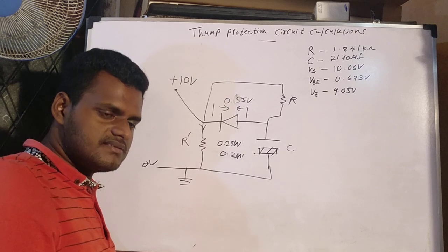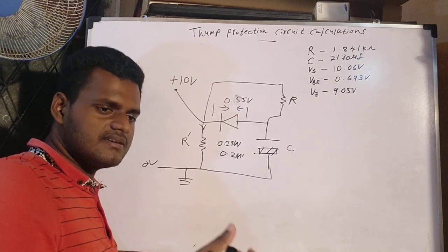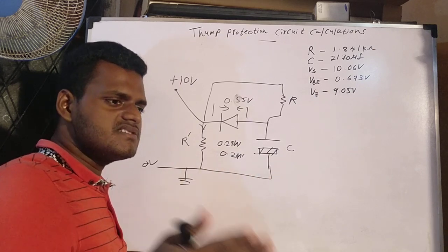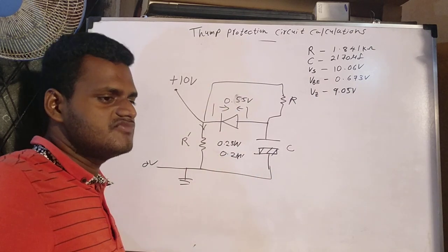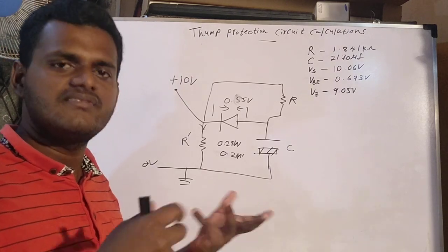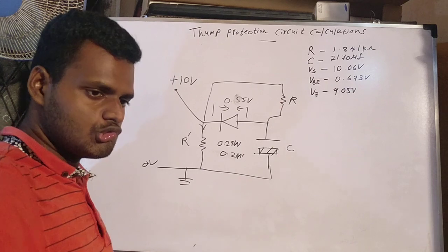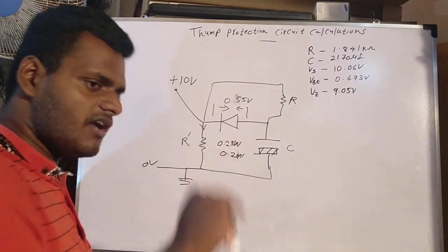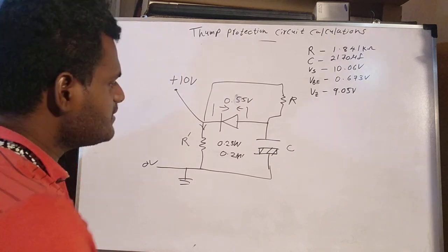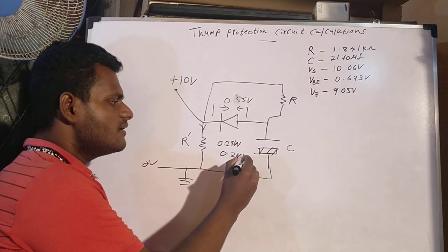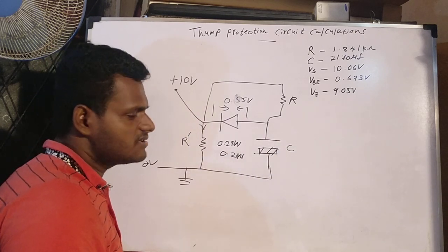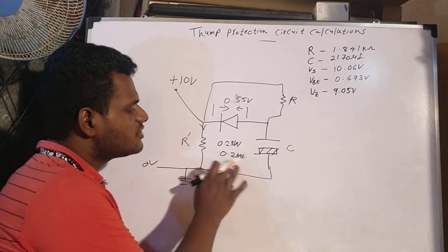If somehow it increases the energy again, the resistor will also burn. Otherwise, after some time, maybe 1 year or so, the resistor will also get damaged. So we have to do a perfect calculation and then find the better value. So I'm taking 0.2 watt, because that avoids the probable cases. So I'm using 0.2 watt.